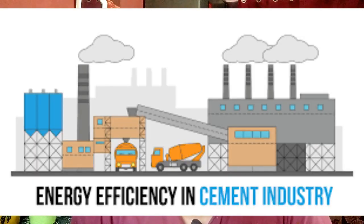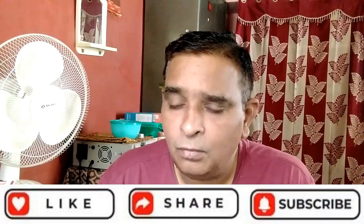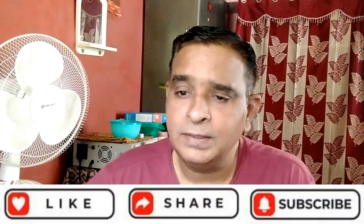And next point is, what is the cement chemical formula? The principal cementing compound is calcium aluminate, CaO Al2O3. Calcium aluminate, that is the chemical formula. And next point is, why is gypsum added to cement? Gypsum is added to control the setting of cement. If not added, the cement will set immediately after mixing with water, leaving no time for concrete placing.